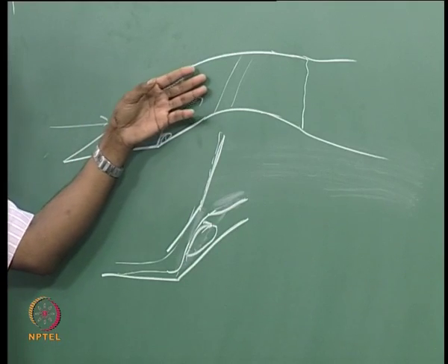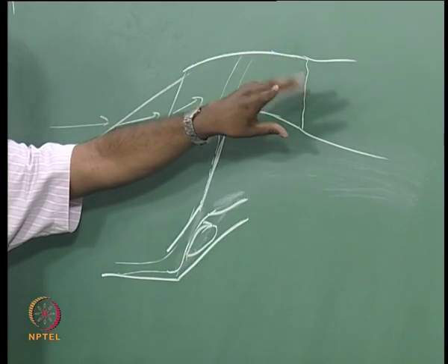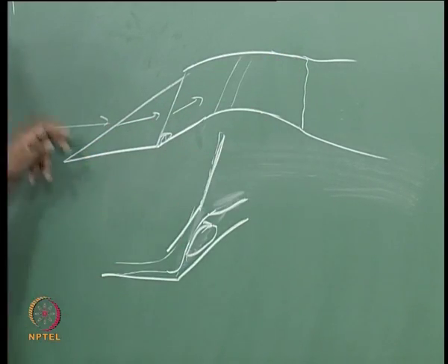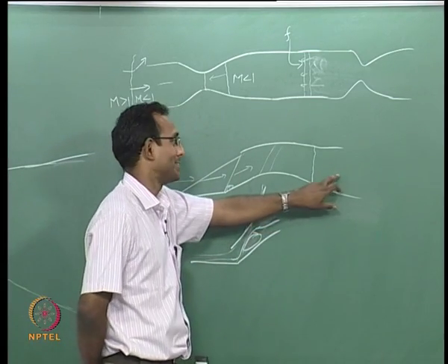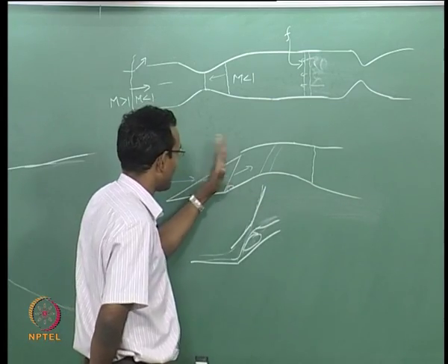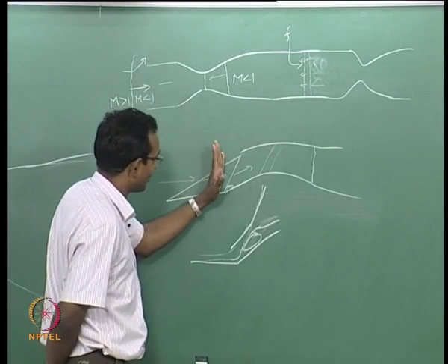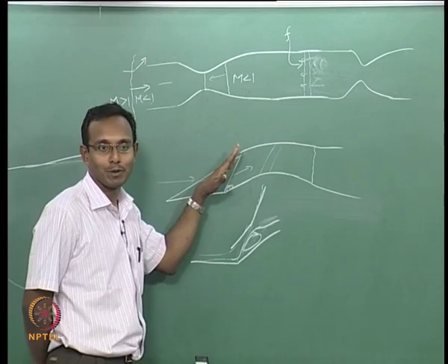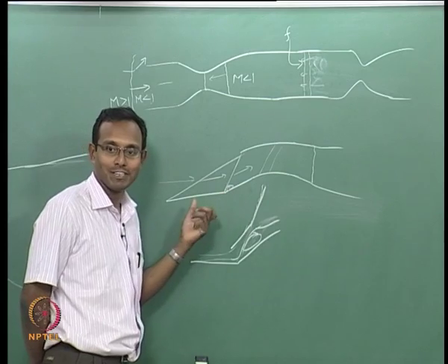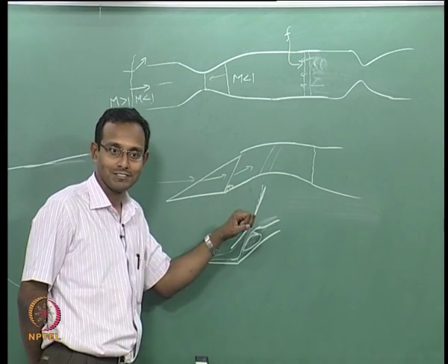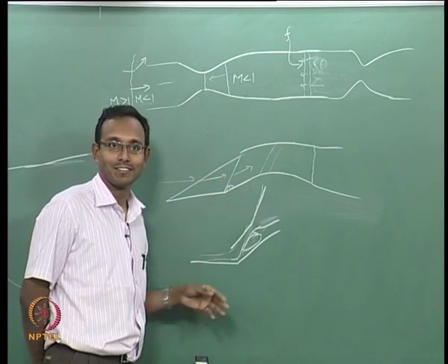The mass going in decreases and there is no extra mass added inside. What will happen? Slowly the mass inside decreases, pressure decreases. So it is like the system is experiencing a lower back pressure. If it experiences lower back pressure, slowly the shock will be pulled in. The shock is getting pulled in, suddenly the oblique shock is more and more oblique. They are lesser P2 by P1. If it is lesser P2 by P1, this boundary layer tripping need not be very strong. The bubble decreases in size. And when the bubble decreases in size, there is more mass flow going in because it is the opposite effect.